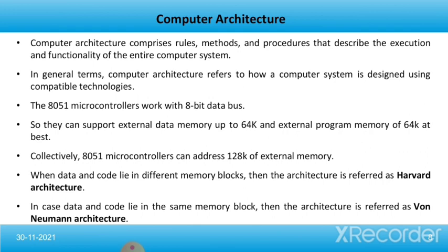So they can support external data memory up to 64K, and 64K is like 2 raised to 16. With an 8-bit data bus, the data memory is up to 64K, and the external program memory is also 64K at best.